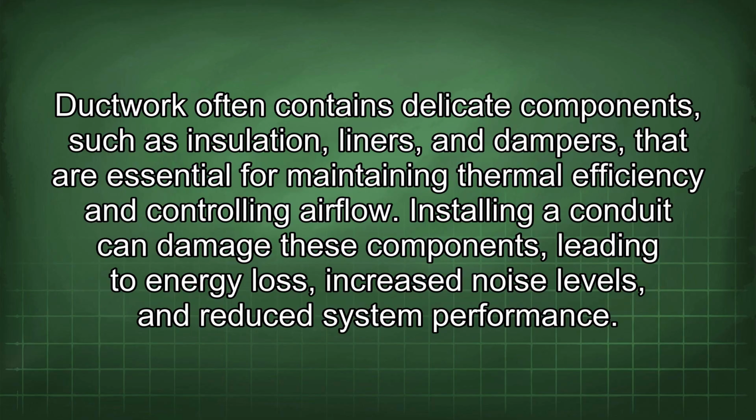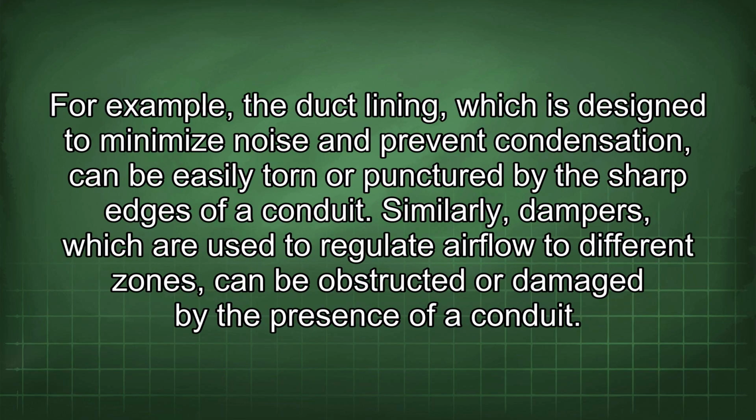Ductwork often contains delicate components such as insulation, liners, and dampers that are essential for maintaining thermal efficiency and controlling airflow. Installing a conduit can damage these components, leading to energy loss, increased noise levels, and reduced system performance. For example, the duct lining, which is designed to minimize noise and prevent condensation, can be easily torn or punctured by the sharp edges of a conduit.